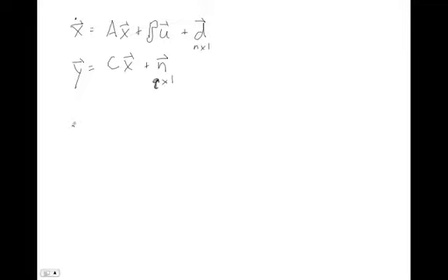So we've designed a closed loop observer. We started with designing an open loop observer for x. That's this simulation of our plant that we run in parallel to our actual system, and we do this in order to estimate the states for full state feedback. We said we can implement an open loop observer, but it's not really great because we're stuck with the stability and time domain properties of our original system. We'd like to have our stability properties be always stable, and we'd like our time domain properties to be probably much faster than the plant we're trying to control.